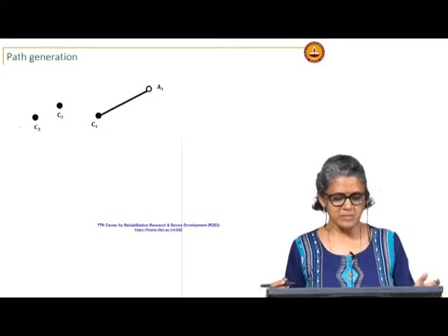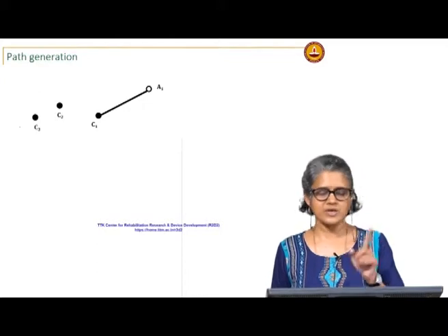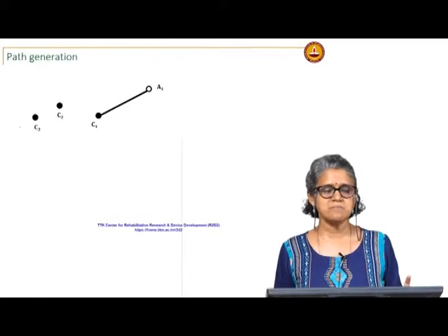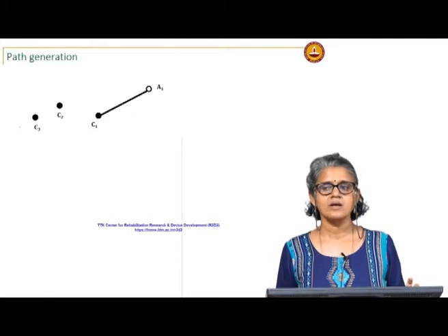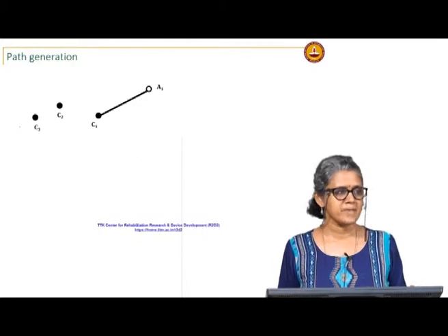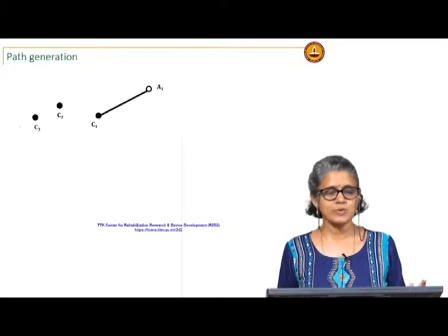So, C may or may not be a pivot. First of all, can C be a moving pivot? If you say yes, you have to tell me under what conditions C can be a moving pivot. If C is a moving pivot, what do I have to do?